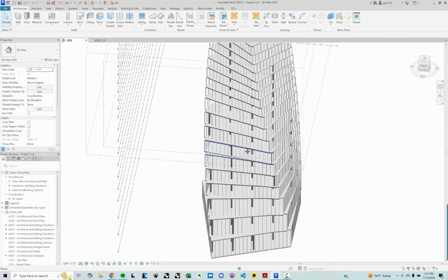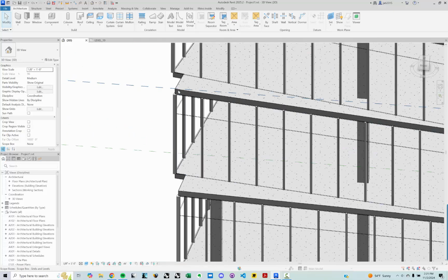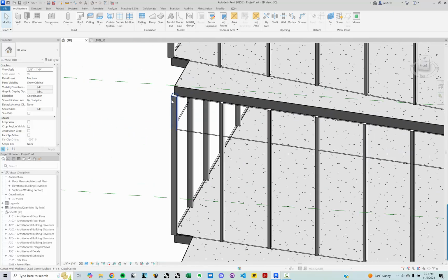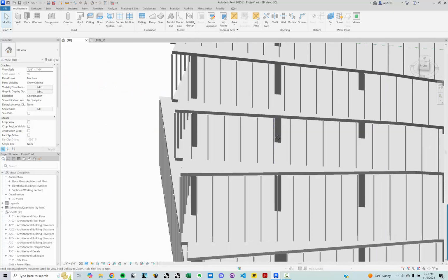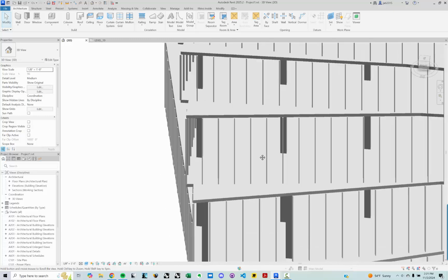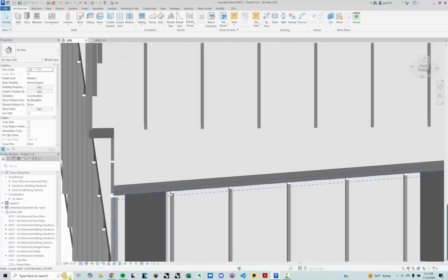This video is about 30 minutes. It took us that long to get it in the right spot. So this here is like mullion detailing. Again, you might actually want to inset the curves. You might want to offset these curves in a little bit to try to avoid this, but that just comes down to detailing. That's how your curtain system interacts with your slab and all of that, because the actual glass itself is okay and in line with the slab, but the mullions are sticking out.